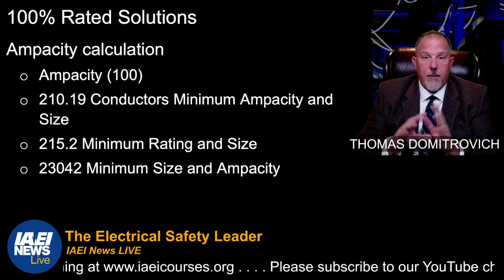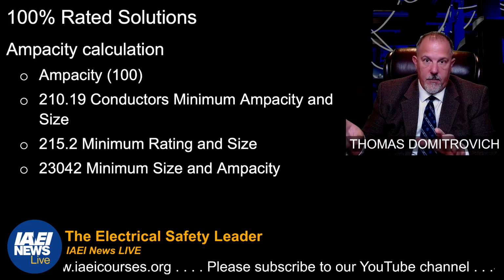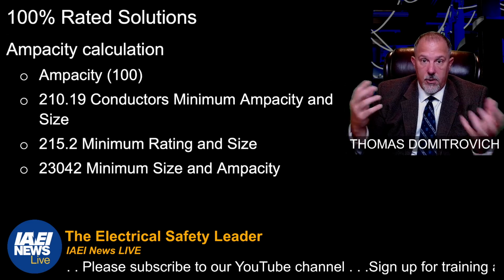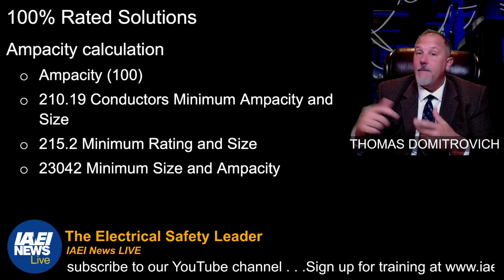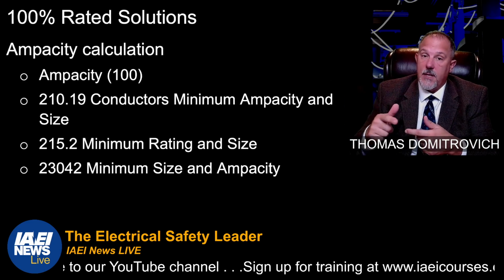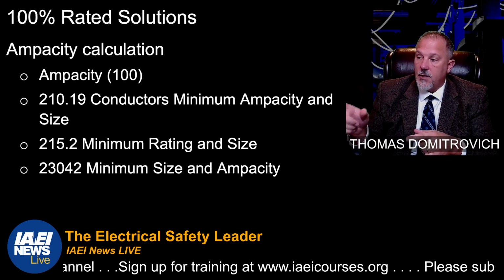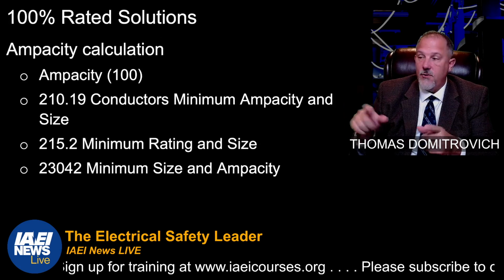So I'm looking at how many conductors are in a raceway. I'm looking at the temperature. Those are the two that I'm going to apply. I don't do that in the first one, but I do it in the second one. Now, there is an exception. There's one exception to 1 and 2.